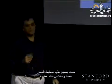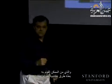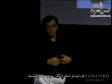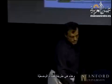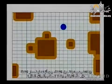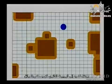And so then we just have to plan a path for one point in that space, which can be done many different ways geometrically. These grown obstacles are called C-space, configuration space obstacles, and this is a C-space planning approach. We can put a grid around it and plan the path of the point around this grid so that it doesn't collide with the grown obstacles. Then when we get back to the circular robot, it's not going to collide with the obstacles itself.